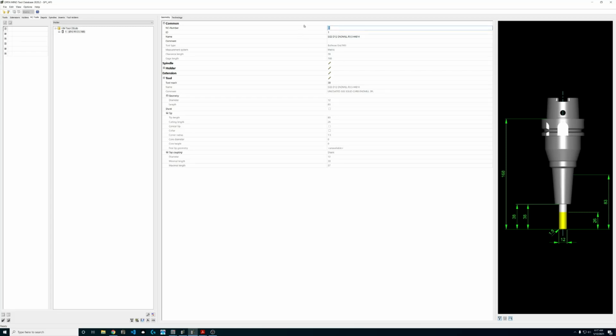At the top, we can assign a number and ID. These may or may not be useful depending on how you have your tools called. If you had it called by name, then the tool had to have been defined in the machine with this entire name here. If it's a number, it's going to use that number. IDs are important, but for reasons we're not going to cover today, sort of with tool redundancy and automation and kind of where we're headed in the future. But that's a brief overview of putting some tools together inside hyperMILL.